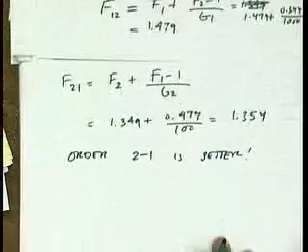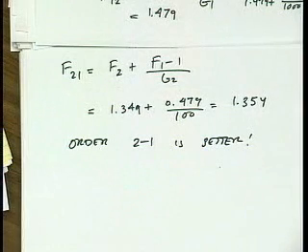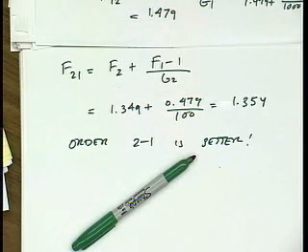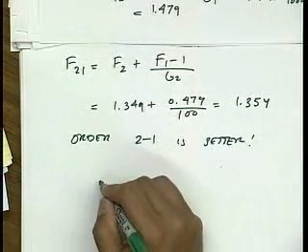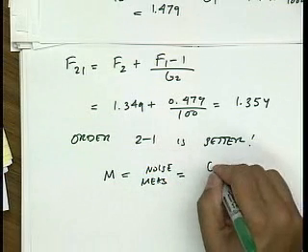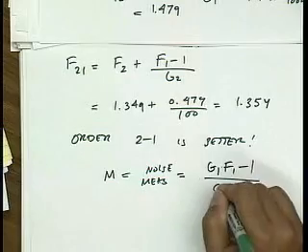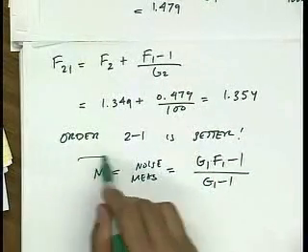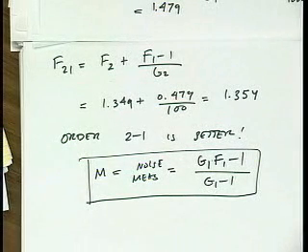Very simple. Okay. Now this seems like a very simple problem, but if you think about this for a while, you actually come up with a really interesting noise metric. So the noise figure as a noise metric has some problems, right? One of the problems is a classic question: what's the noise figure of an ideal wire? It's 0 dB, right? An ideal wire has no loss, but it also has no gain, so it's not really that useful. So somehow it would be nice if we had a noise metric that took gain into consideration. Okay? And it turns out that if I calculate M, which is called the noise measure, which is defined as the noise figure minus 1 divided by 1 minus 1 over the gain, then this noise measure is a better way to characterize a device than the noise figure alone.